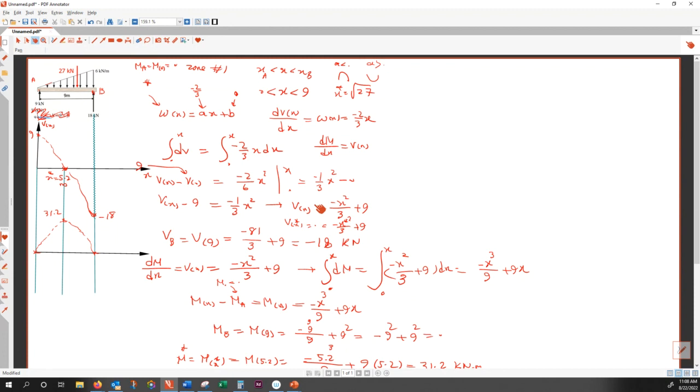40.5 from the left. So you mean that x star is 5.2? Is that what you mean? I don't know, 4.5. Is that what you mean? Yes, yes, 5.2. But you know, Lachlan, that answer is not 100% correct. This is where the bending is most critical. But from shear perspective, the critical point is point B, isn't it?